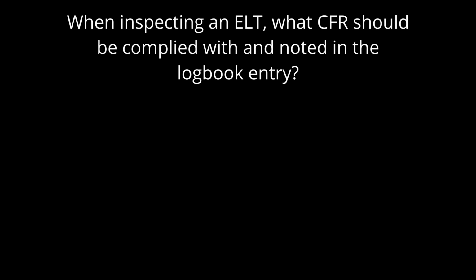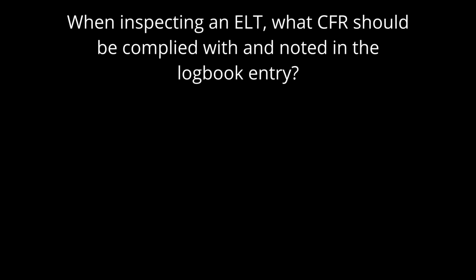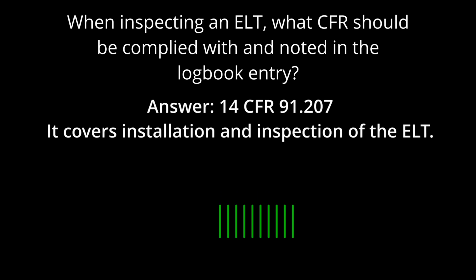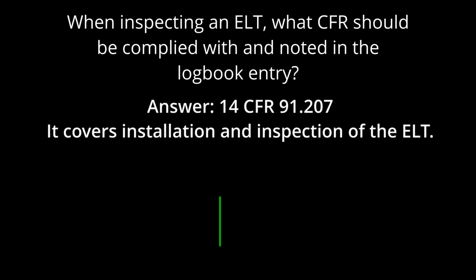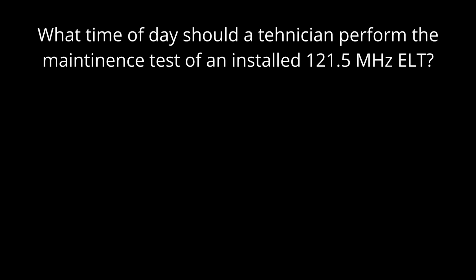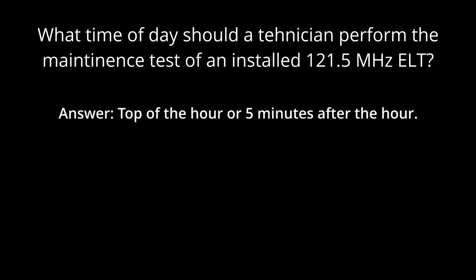Whenever you inspect an ELT, there is a CFR that you must always comply with, and so noted in your logbook entry. What is that CFR? 14 CFR 91.207. Yep, 91.207. Mostly what that CFR covers is inspection of the ELT as well as installation. What time of day should a technician perform the maintenance test of an installed 121.5 megahertz ELT? The first 5 minutes of the hour. Top of the hour and 5 minutes after the hour.